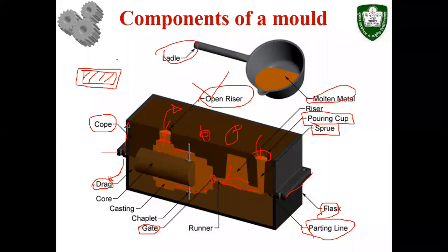Exactly, at the melting point temperature, the volume increases, but you cannot just pour the molten material at the melting point temperature, because if you pour it, it will be solidified instantly. That's why you need to heat up the liquid metal further. If the melting point is 700 degrees Celsius, then you heat it to 800, 900 degrees Celsius, so that you can give it proper time to flow into the cavity before getting solidified.